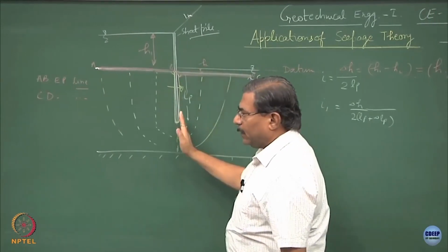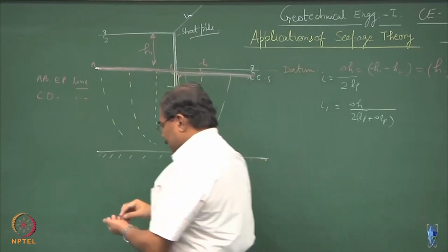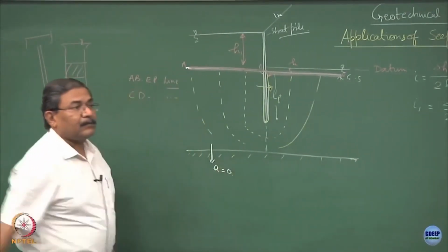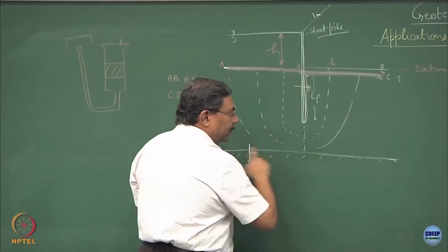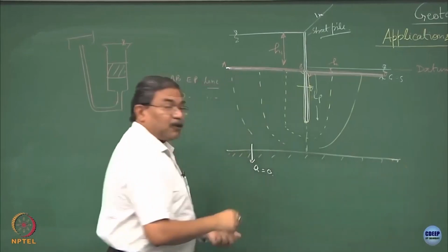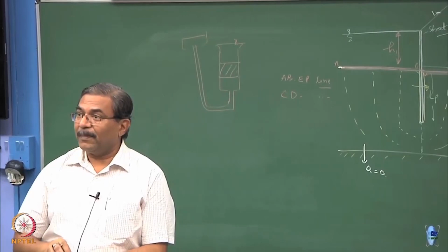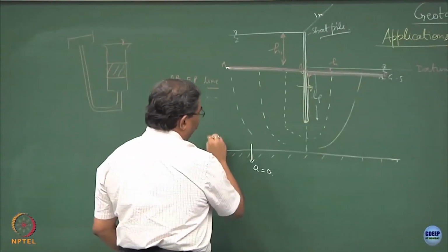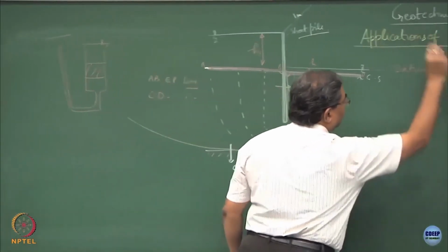Equipotential line, flow line, across this no discharge is going to take place. This is the porous media. Similarly, across this there is no discharge, because it is an impervious surface. Now if there is no discharge across this line, this is also going to be a flow line. Agreed? Correct? So that means the bottommost flow line would be something like this.